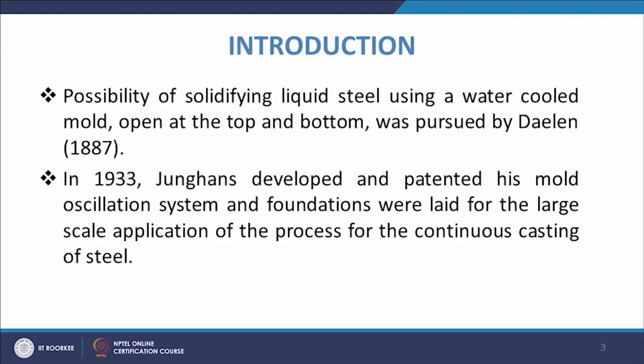Now, the possibility of solidifying liquid steel using a water cooled mold open at the top and bottom was pursued by Dellen in 1887. In that, you have a mold which is water cooled and also open at the top and the bottom, and that is basically the working principle of continuous casting.